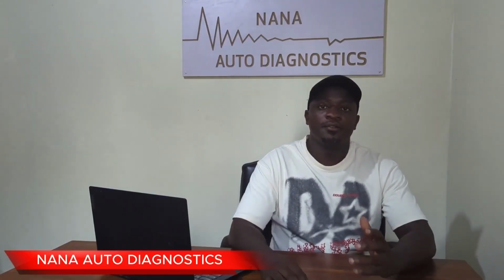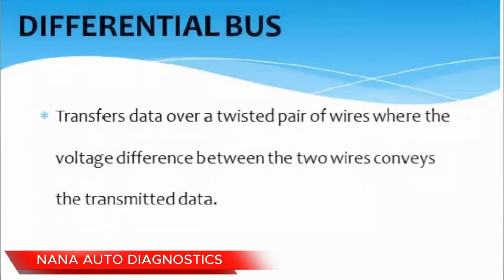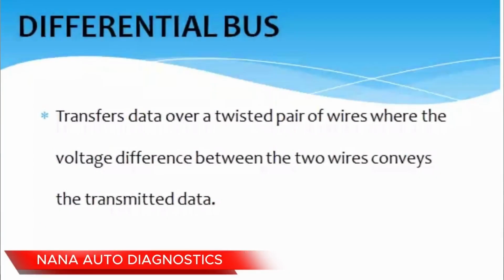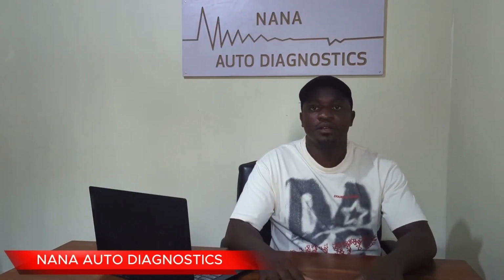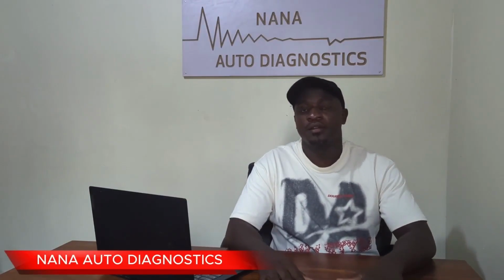And for the differential bus networks, these transfer data over a twisted pair of wires, where the voltage difference between the two wires conveys the transmitted data. The differential bus network finds its application in communication networks such as CAN, which is Controller Area Network, and FlexRay.